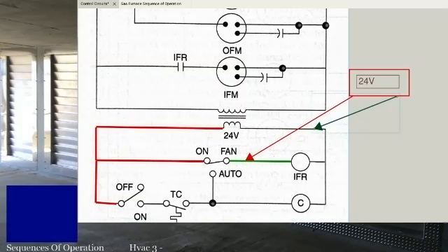And when it does get you in trouble, if you're not used to that method of troubleshooting, if you're not used to keeping that lead right on common and testing everything else after it, you'll be trying to diagnose something for a lot longer period of time than is really necessary. So that's the hopscotch method of troubleshooting. I just wanted to bring it up in case your book doesn't cover it later on. You always want to keep one lead on common or one lead on neutral.